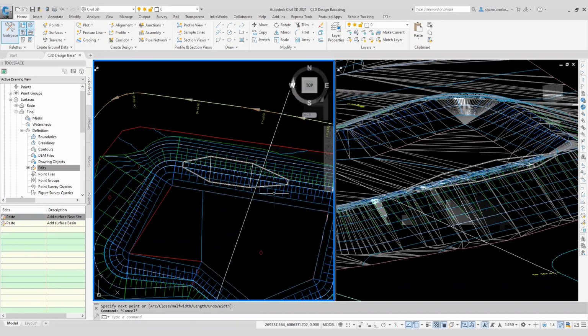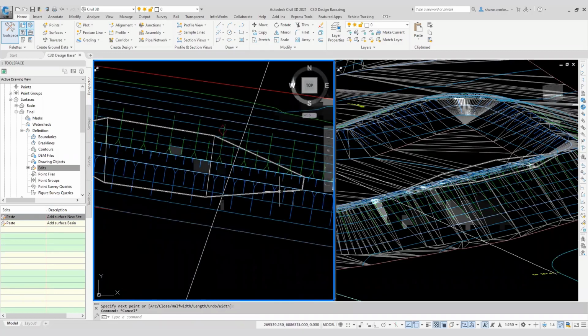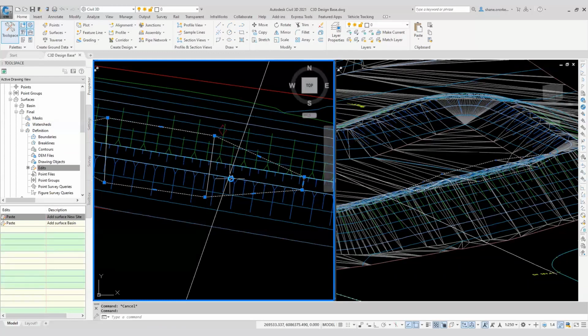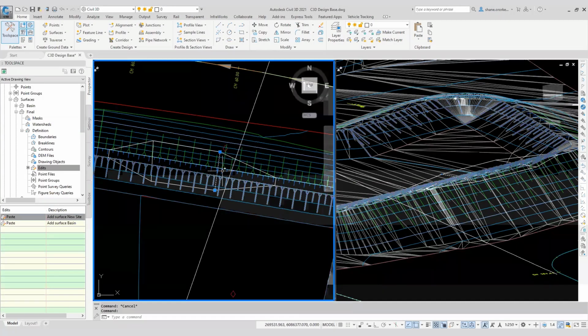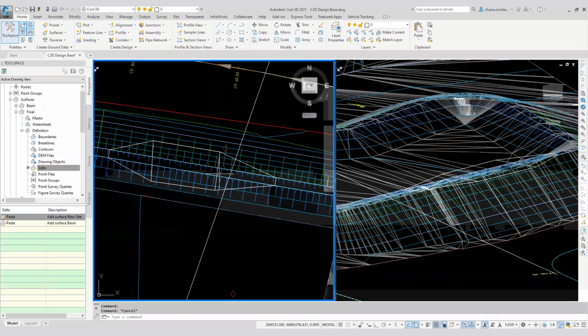Let's do it. We're going to create a feature line here. We're going to drape it onto the wall, so you'll actually see this will glue onto the wall. And then we're going to create a secondary feature line that will just go straight across. Now, this feature line in particular is not going to use the levels of the other feature lines. I need to put it in a new site.